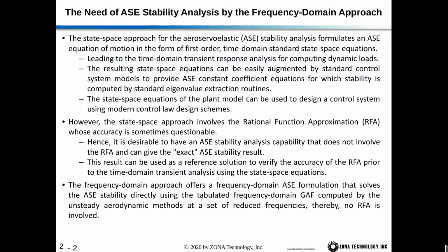And this result can be used as a reference solution to verify the accuracy of the RFA prior to the time domain transient analysis using the state space equations. This frequency domain approach offers a frequency domain ASE formulation that solves the ASE stability directly using the tabulated frequency domain graphs computed by the unsteady aerodynamic methods at a set of reduced frequencies, and therefore no RFA is involved.